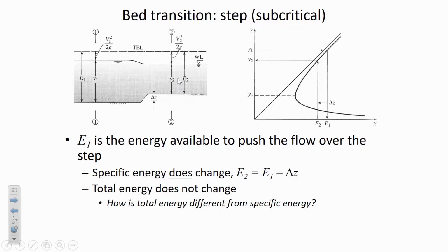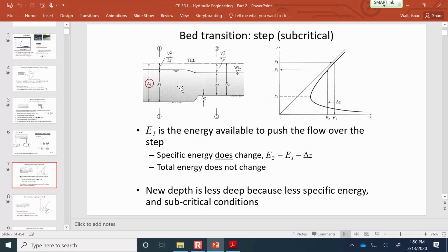And this is really counterintuitive. Think about it. The water has to flow over an obstacle, but because it flows over the obstacle, now it's a shallower depth, which means it has to flow faster. So having the step that the water has to flow up over actually increases the velocity of the flow. That's one of the first of a few head scratchers where the water is doing something that initially you maybe wouldn't have come to that conclusion when you first looked at it.